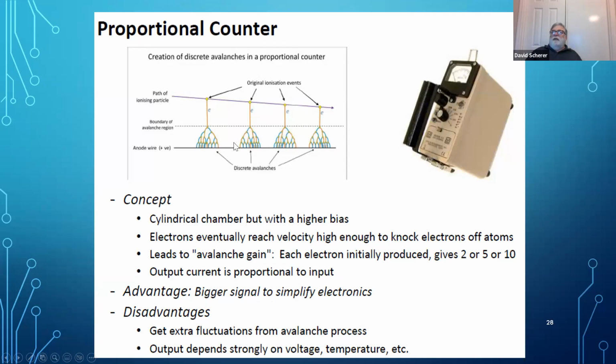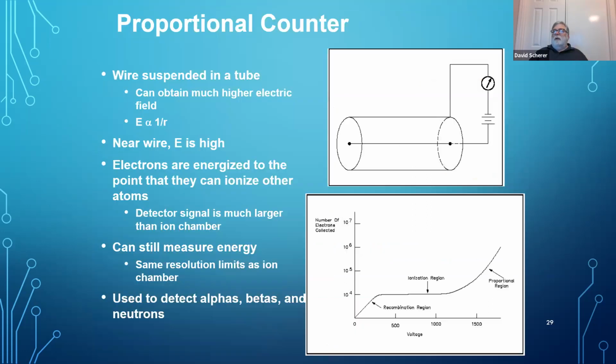Okay, now this amplification process looks pretty uniform here, but more variation is introduced because there's some fluctuation that takes place in this amplification process. Sometimes there's more charge produced, sometimes less. There's an average that you would see, but you'd see some variation, some dispersion.